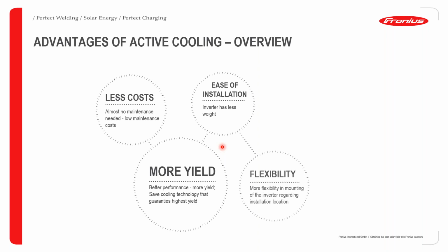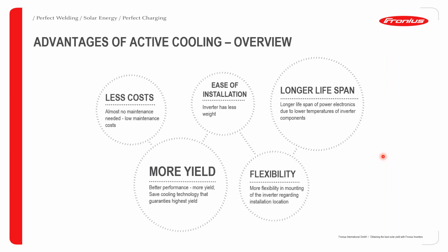cost of installation. An actively cooled device also gives you a lot of flexibility, as you're going to see later. So with the Fronius inverters, you're not limited on where you can install the inverters. And most importantly, an actively cooled inverter will have a longer lifespan than a passively cooled device. This is also very important for your customers.